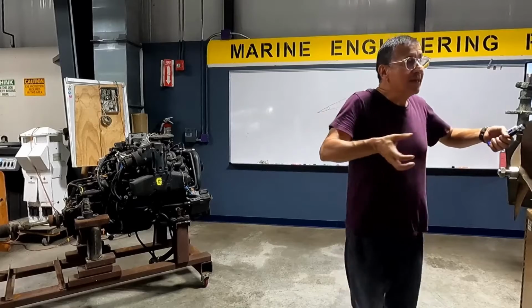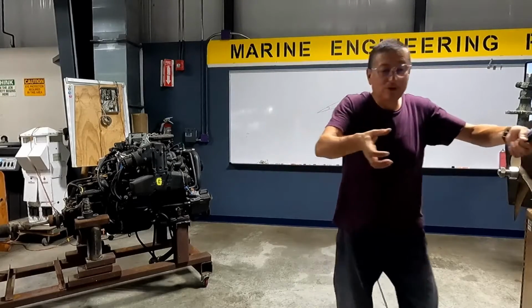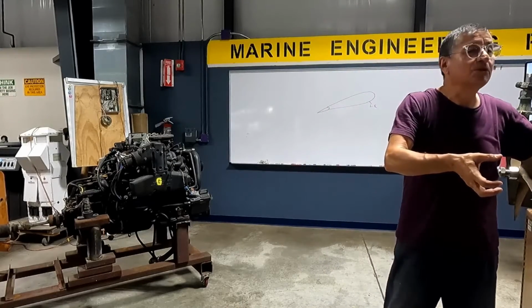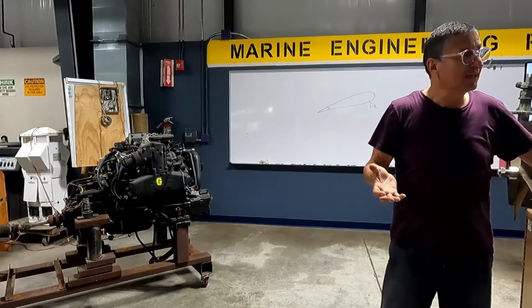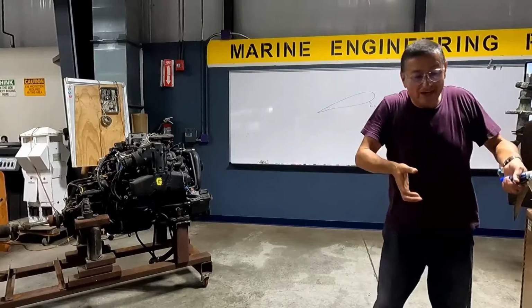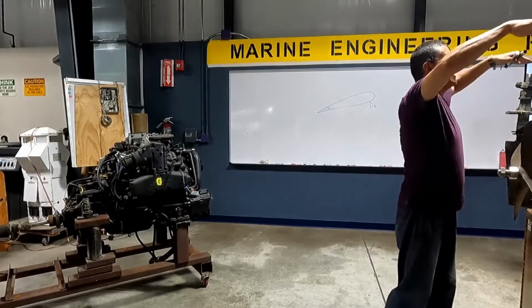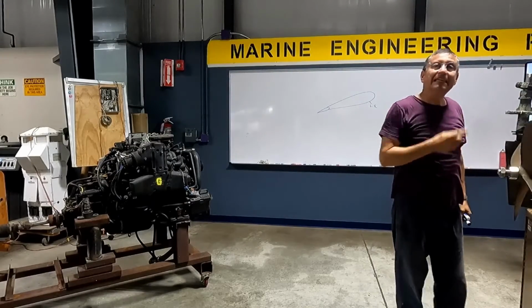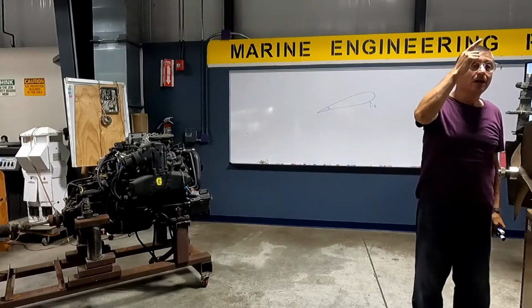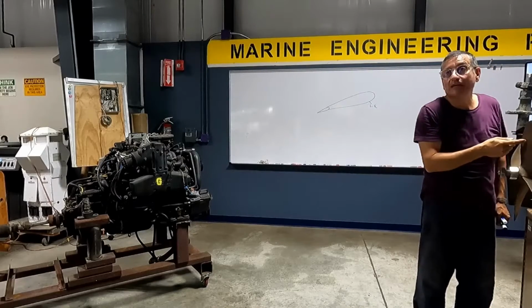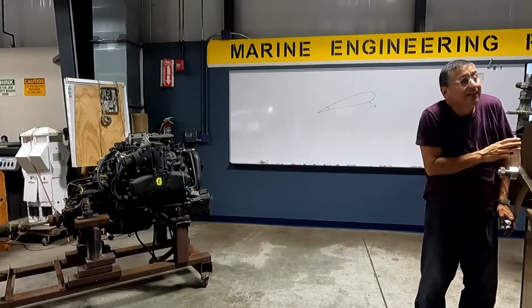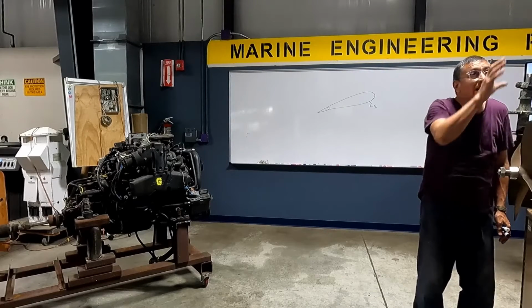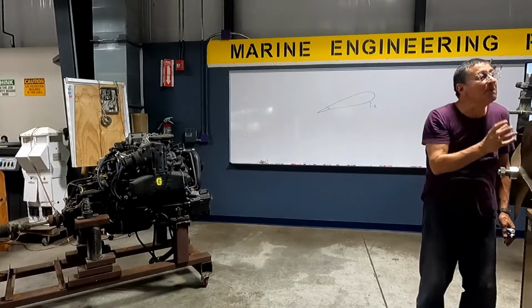Depending on where you locate the generator inside of the boat, you can introduce vibration, harmonic distortion in the boat. If you locate the generator inside of the boat over the propeller here, the generator is spinning at 1800 RPMs. And this one is spinning in some cases at 1000, 1200.